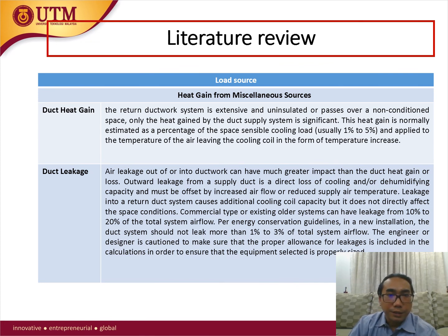Duct leakage. Air leakage out of or into ductwork can have much greater impact than a duct heat gain or loss. Outward leakage from the supply duct is a direct loss of cooling and/or dehumidifying capacity and must be offset by increased airflow or reduced supply air temperature. Leakage into a return duct system causes additional cooling coil load, but it does not directly affect the space condition. Commercial type or existing older systems can have leakage from 10% to 20% of the total system airflow.